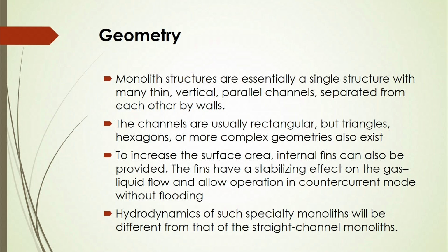And in this case fins are one of the important geometrical effects, where they can give a stabilizing effect on the gas liquid flow and allow the operation in counter current mode without flooding. So, that is why internal fins are sometimes advisable to procure or design in the reactor to get the stabilizing effect. And the hydrodynamics of such specialty monoliths will be different from that of the straight channel monoliths. So, these are the different geometrical effects on the performance of the monolithic reactors.